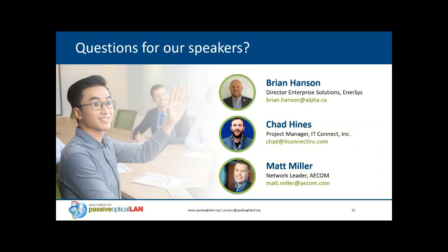Okay. I got a power one for you, Brian. If the building has existing UPS and eGen, won't that cover my backup? Well, the purpose of an emergency generator or an eGen, as you put it, and a building UPS, traditionally those are sized out for the emergency scenarios of the building, i.e. your emergency lighting, exit signs, other what they would deem critical facility systems.